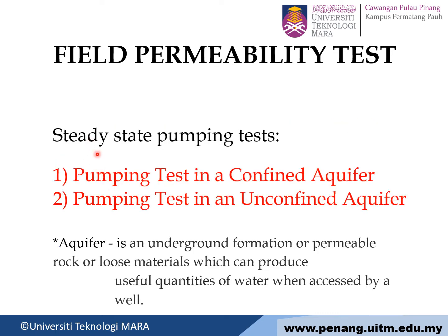For field permeability tests, we are conducting steady state pumping tests. We have two types of tests. First, pumping test in a confined aquifer. Second, pumping test in an unconfined aquifer. What is an aquifer? An aquifer is an underground formation of permeable rock or loose material which can produce useful quantities of water when accessed by a well.